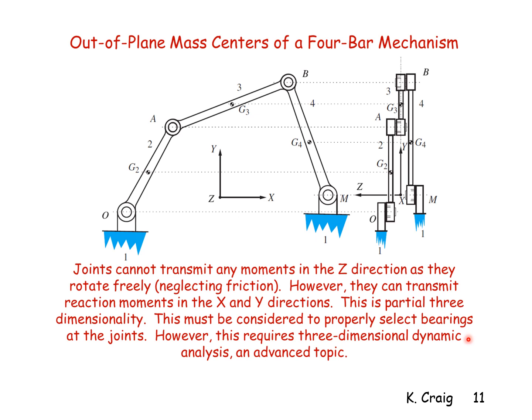However, this requires three-dimensional dynamic analysis, which, as practicing engineers, you'll have to consider and invest time in study to understand. But for now, we're neglecting that. So we're neglecting the physical situation and considering this plane motion idealization, knowing that when you build the actual system, there could be out-of-plane forces and torques that result, that the bearings will need to withstand, and so must be chosen accordingly so they don't fail.